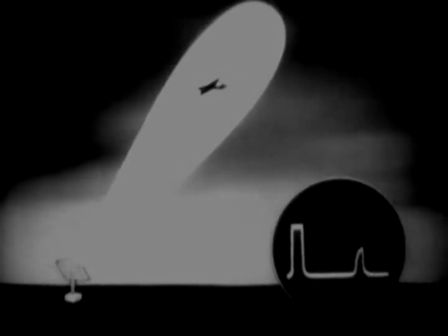But here's why a single pip can't provide accurate azimuth or elevation data. When the target signal on your scope fades, did the plane move ahead of the beam, behind it, above it, below it, or is the signal just fading due to a faulty set? You have no way of knowing. And if you assume the plane's getting away from you and begin searching for it, there's a 50-50 chance you'll traverse in the wrong direction and lose the target completely.